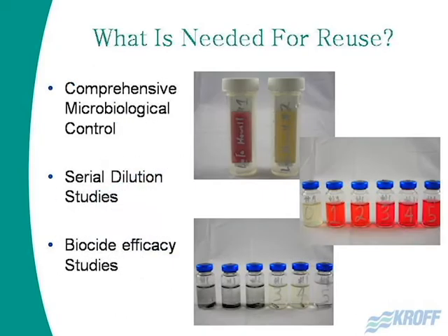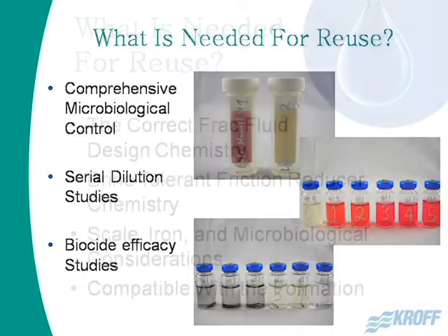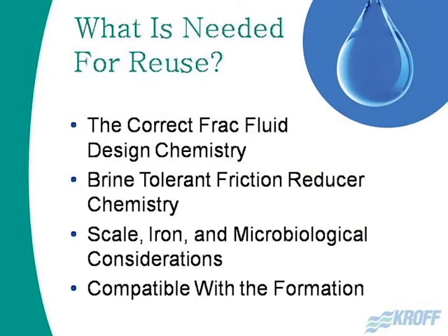Typical microbiological evaluations: sulfate reducers, acid producers, total aerobic bacteria. You don't want slime. You've got a sand filter down there, guys. You don't want that sand filter to get plugged up so that gas can't flow to the wellhead. So you don't want scale, you don't want deposits, you don't want that bacteria. It's water treatment 101. Take those impurities out that form them, feed chemicals that prevent them. Pretty simple stuff.